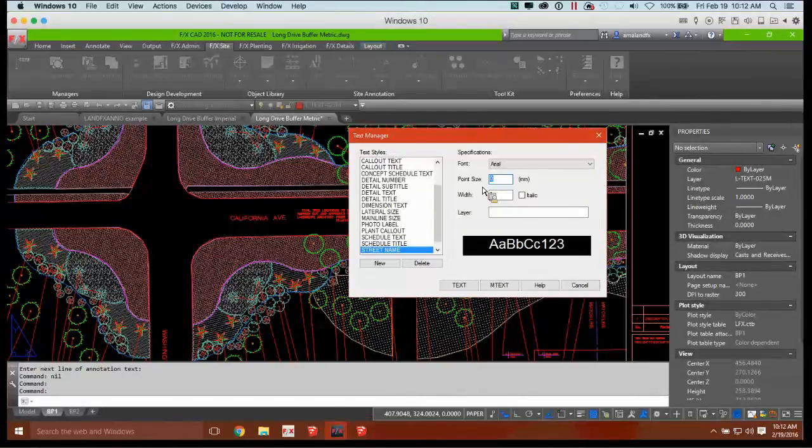And you want it to be consistent. So the way to be consistent on a piece of paper is, just like if you were using a word processor, you'd use point size. You wouldn't say it's 3 meters tall in the drawing or a quarter inch on the sheet or something like that. You would think, well, standards of typography say 12 point is very legible. And for something I want bold, like a street name, I might go something a little bigger, like 18 point. That's very familiar, easy to work with, and doesn't involve too much math in your head.